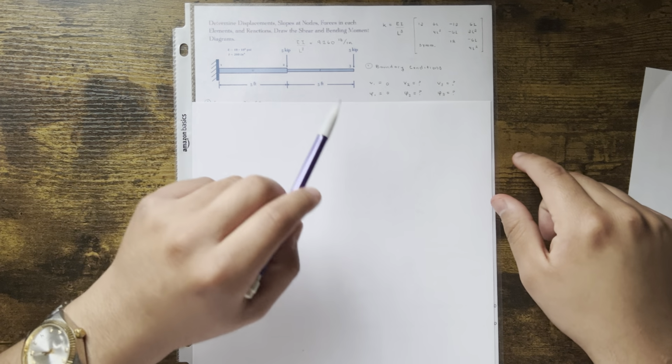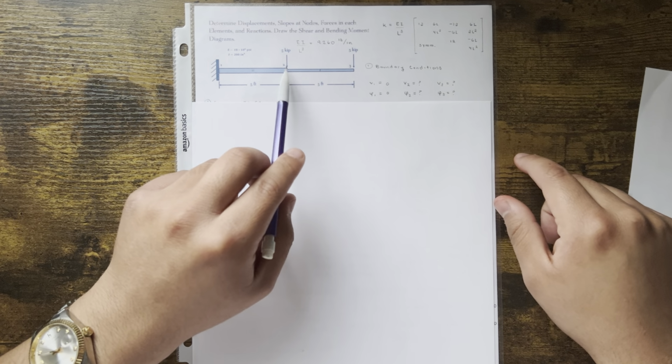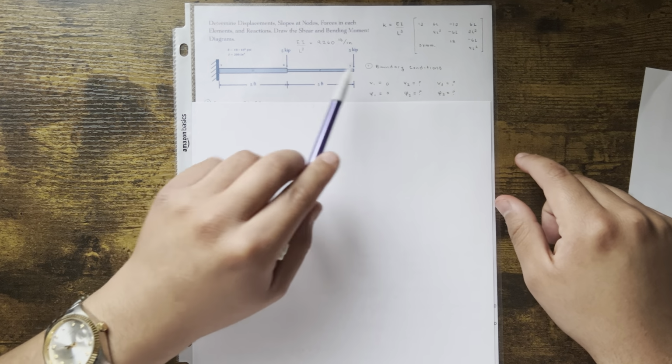So in this case, we don't know the 4 degrees of freedom in these two nodes, right? We only know these two, V1 and Phi1. So if you know these, that means you don't know the force or the moment. And if you don't know V2 or Phi2 or V3, Phi3, that means you do know the force and the moment. Okay, so just something to keep in mind. So once that's done, you go ahead and start assembling the global equation, right? The element stiffnesses before, I'm sorry.